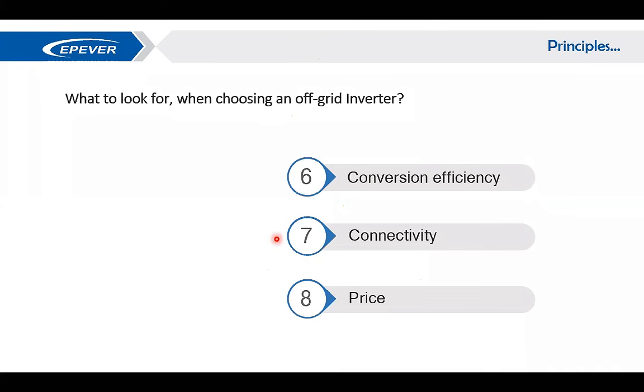So we always need to collect some data from the system parameters, and a good inverter should be capable of providing the data for your monitoring by different means. Nowadays we have Bluetooth, Wi-Fi, or the Internet of Things, and so on. So a system that you're using must be capable of providing you with data over some network, Modbus, HTTP, whatever. You have to get some data out of your system. And this is what we call the connectivity.